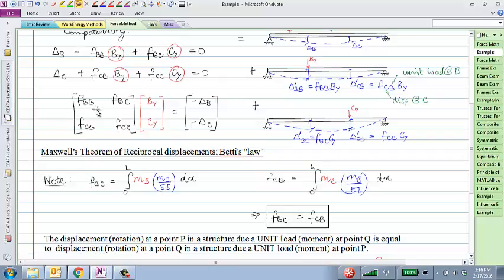If you think of it as a triangular set of flexibility coefficients, you'd be calculating one unknown in the first line, two coefficients in the second, and 3 and 4 and up until 10. So 1 plus 2 plus 3 all the way up until 10. How much would that be? 55, right? Because if you don't remember, that formula is n times n plus 1 divided by 2. That's the number of coefficients you'd be calculating.